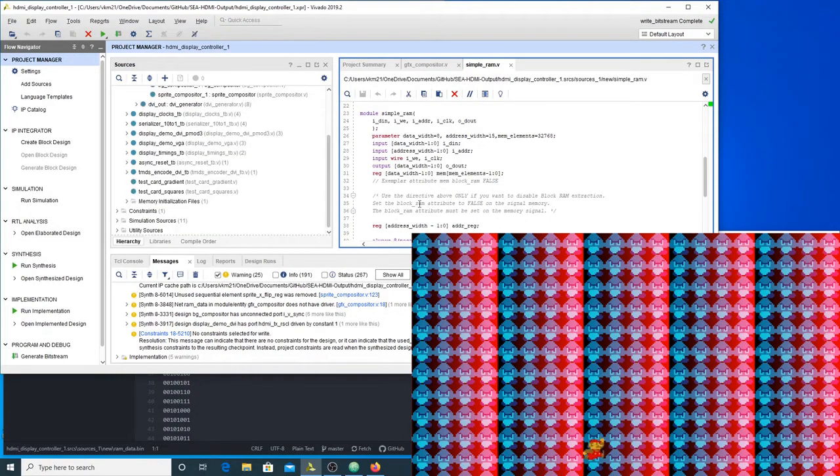So basically, if you write the logic here that describes the function of RAM, right? So RAM, you'd be able to read it, you can write it, you have to give it an address that you want to read from, or you have to give it an address you want to write to, as well as the data you want to write to that address. And it has to be tied to a clock, so you have to take a clock in, and it has to have a certain size, so an address width, maybe a total number of elements that you're going to support, and then you have your register array of data that you want to store.